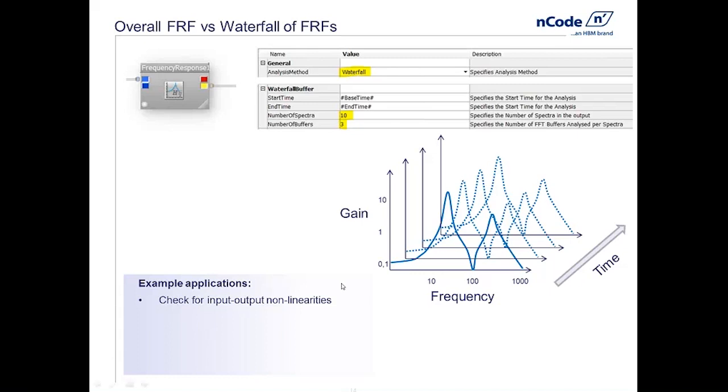And if we were linear, the response on the structure that's fixed to the shaker would increase proportionally, and the gain, being the ratio between output and input, should not change. If at some point in time it does change, it means that right from this amplitude and above, I see clearly some non-linearities in my structure. So I can no longer consider it linear.